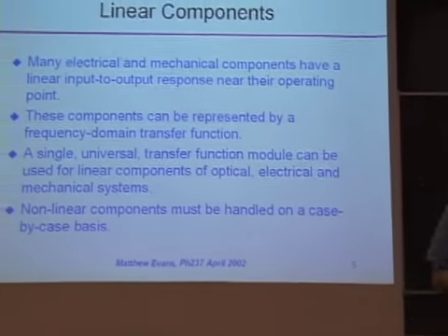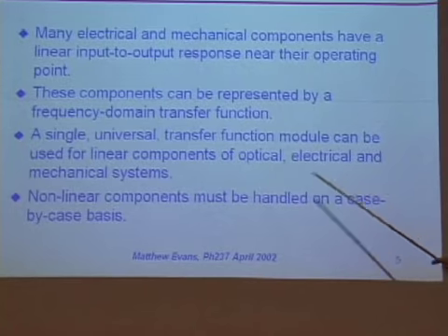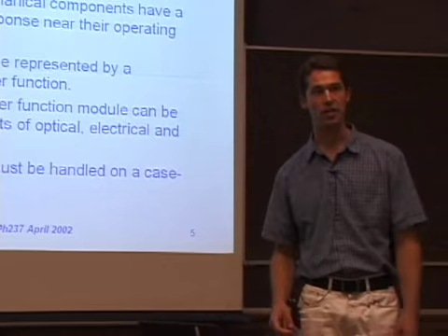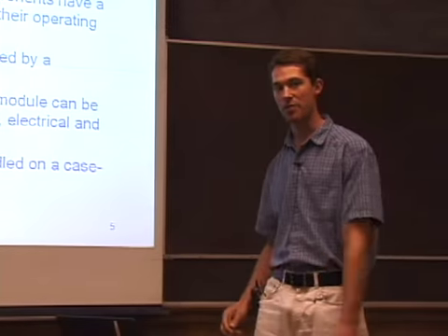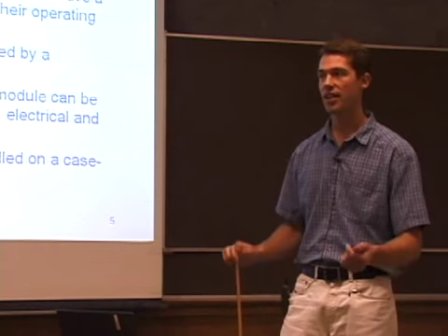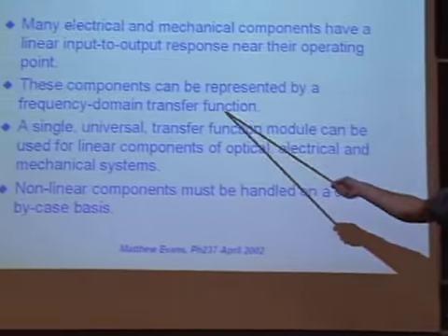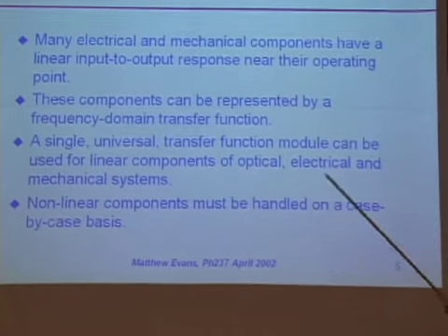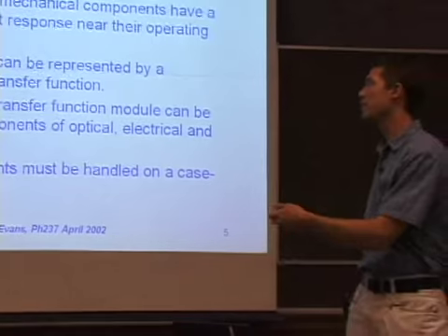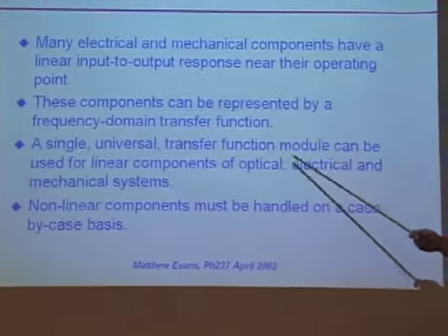A brief interlude before I get to electrical and mechanical components. I talked in the beginning a little bit about frequency domain and linear response. There are a lot of things that are electrical and mechanical which have a linear response, and just because we're doing a time domain simulation doesn't mean we should ignore that fact. So we have a generic transfer function module, which allows us to take any frequency domain representation and represent it in the time domain. You can feed some input in, it'll apply the appropriate transfer function and give you output. So these things are useful for analog filters, digital filters also, anything which has just a linear response.